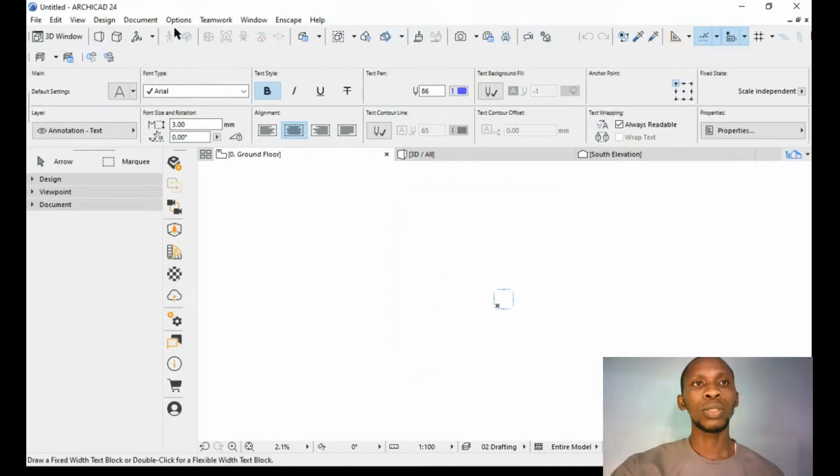Right, so now let's continue. We have the pen set. One of the things that is important in your drawing in Archicad is scale. So number two is pen set. Once you open your Archicad new layout like this, the things you want to set out first: number one, set your scale. Make sure it's on 100 or 200 depending on the paper size. Secondly, you want to set your pen set.